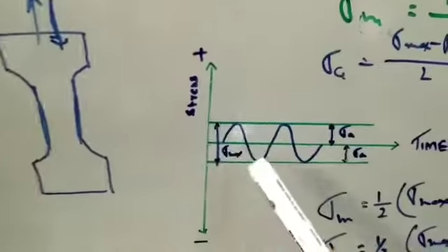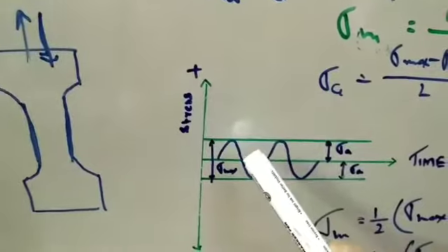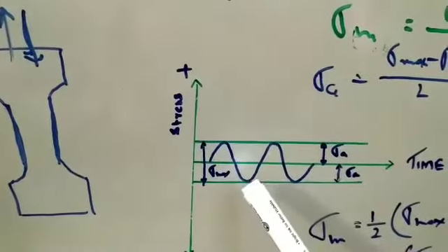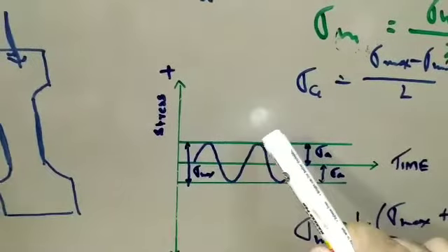You could see as you are pulling this specimen, the tension moves up. Now what happens? The tension reaches a maximum, the tension reduces to 0. Then compression starts. It is compressing, and compression becomes maximum. Then again it moves up, compression 0, then again it is tension.